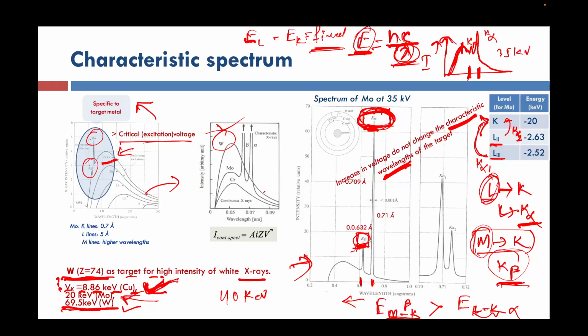You can see the variation in wavelength is less than 0.001 angstrom. Even this much we would want to separate, one being K alpha 1 and another K alpha 2. So whatever information we get always carries contributions from both radiations, that means K alpha 1 and K alpha 2.